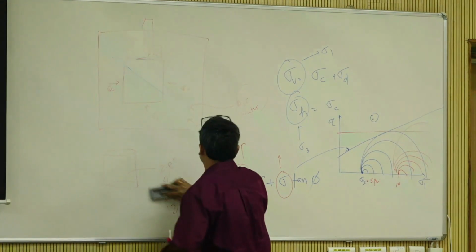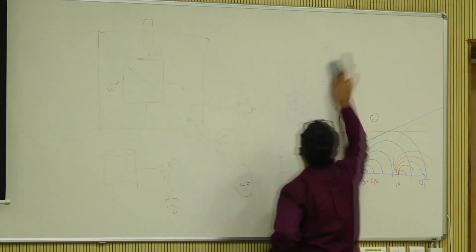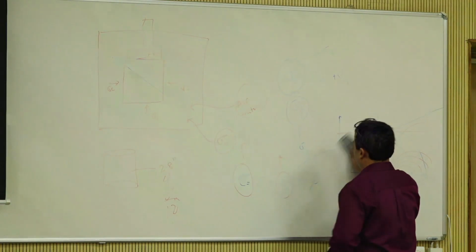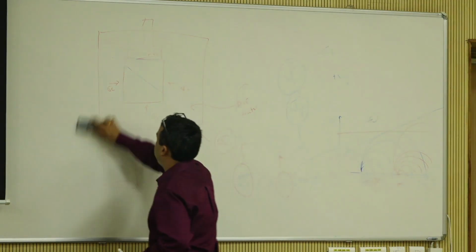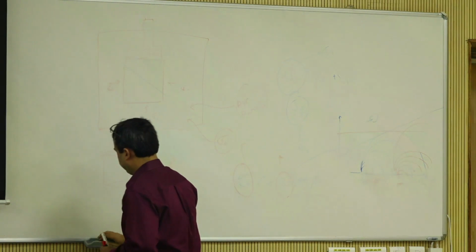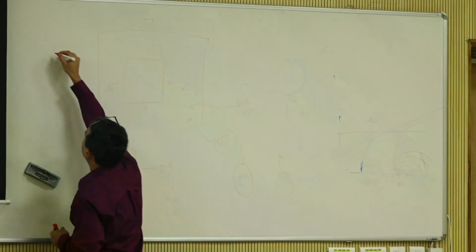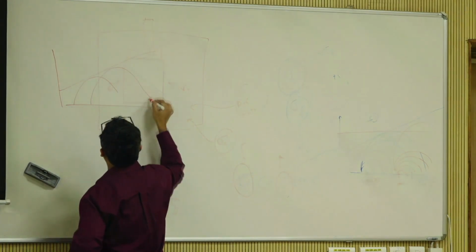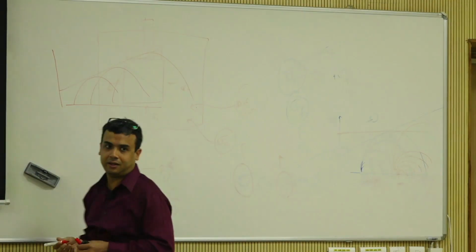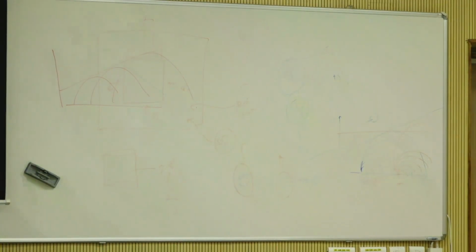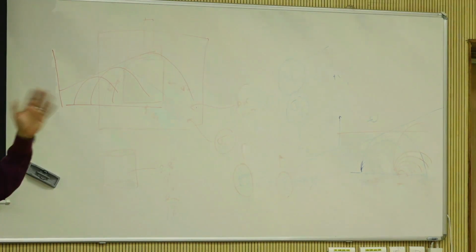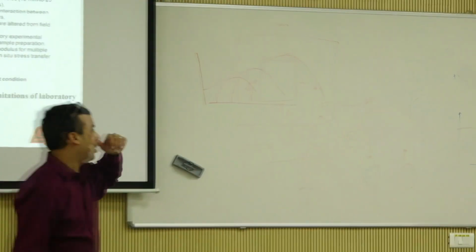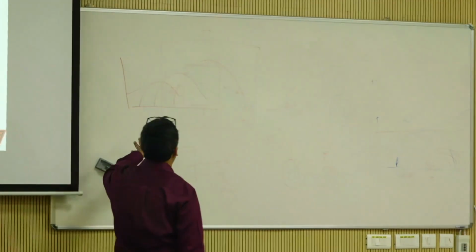But the bottom line is you are going to use a Mohr Coulomb failure envelope, which is going to give you, so just do this, maybe like one circle here, one circle here, one circle here, and that's what a typical triaxial testing does, right? When you go into pure geotech, you can go into all the different forms like unconsolidated undrained, consolidated undrained, consolidated drained, unconfined compression and stuff like that.